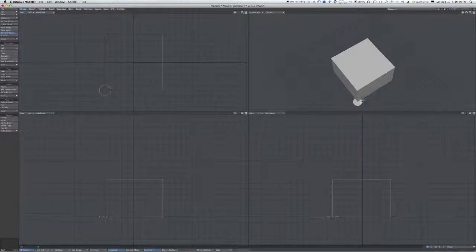So if you add a little tab like this, you make it just one layer thick, 1 or 2 layers thick. So if you're printing with a 0.35 millimeter nozzle, make it 0.35 millimeters thick. If you're printing with a bigger nozzle, then of course you have to make it that size. But if you put one of these on each corner, it will help hold this down. And when you're done, this can easily be removed because it'll be thin. It'll be 1 layer thick. So you can just use a sharp X-Acto knife to cut that off real easy. And it's a quick, easy way to help hold your parts down.